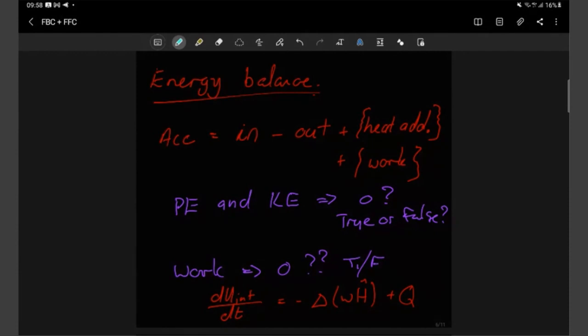then that form of work might be important in terms of energy balance. If you have a small hot plate stirrer with 1 or 2 or 3 milliliters of stuff in it, it might be important. Or if you have a massive rotary kiln, the actual work done by that might cause some effect. So be careful of just assuming it's zero. Do a back of an envelope calculation, check yourself, and then sure, if you are making this assumption that potential or kinetic energy is zero or work is zero, just check it quickly and go from there.